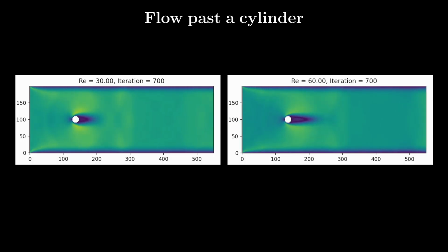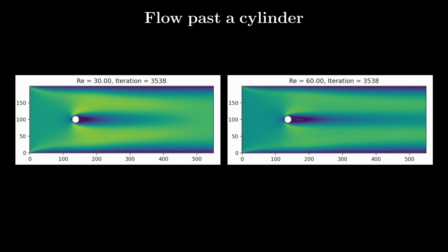We first look at flow past a cylinder. At low wind speeds, velocity fields are relatively uniform, with the fluid flowing smoothly across the edges. When wind speed is increased past a threshold, around a Reynolds number of 60, regular oscillations start to form in the wake of the cylinder. This well-documented phenomenon is known as vortex shedding. The oscillation is so well behaved at low Reynolds numbers that there's a formula that can be used to determine its frequency.